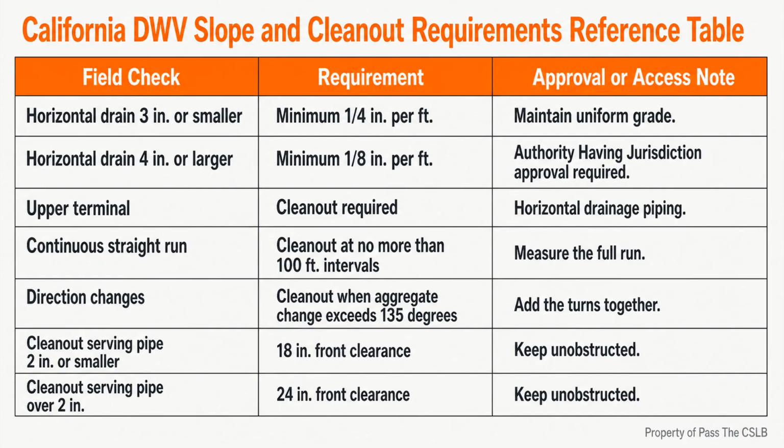Consider a hypothetical hillside house with a lower level bathroom. If those fixtures sit below the next upstream public sewer manhole cover, a sewer surcharge can seek relief through the lower fixtures. An approved backwater valve acts as a one-way barrier against reverse flow. The supervision issue is to recognize the condition early enough to coordinate an accessible valve and the associated service access before finishes close the area. A backwater valve is not a substitute for ordinary drainage design, and it is not a device to add to every building without analysis. It is protection tied to a defined elevation condition.